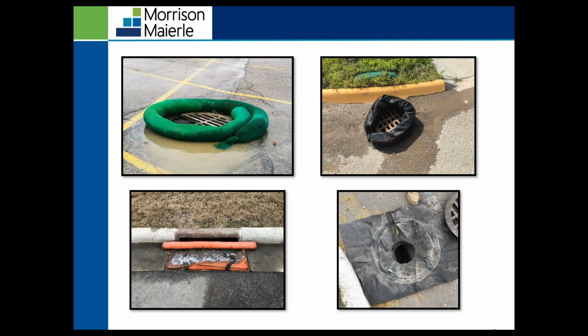Here are just 4 different examples of inlet protection. Sediment control right here. These BMPs are designed to capture sediment before the stormwater discharges into the inlet. That inlet has a direct route to our state waters. There's a lot of options to use for inlet protection.